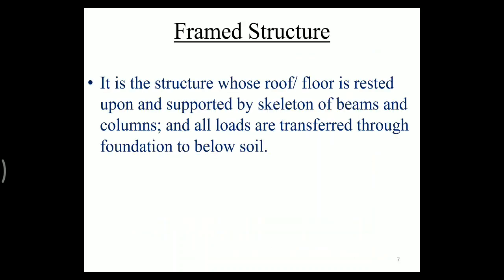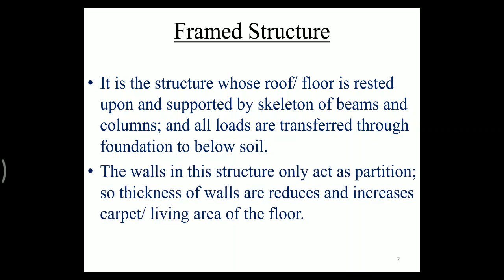Now we see the frame structure. It is the structure whose roof or floor is rested upon and supported by skeleton of beams and columns, and all loads are transferred through foundation to below soil. The walls in the structure only act as a partition, so thickness of walls is reduced and it increases carpet and living area of the floor.